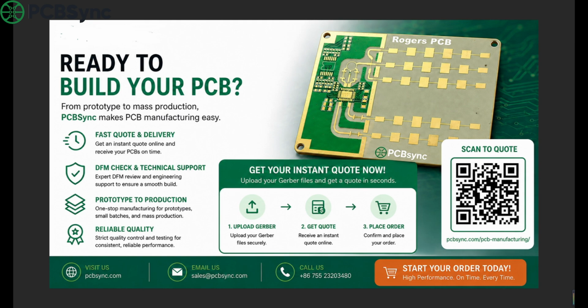In short, RO4003 is more processable than PTFE alternatives, but key challenges remain in stack-up, impedance, dimensional compensation, and supply stability. When designing, use the correct design DK, and before production confirm the actual material copper thickness, finished board thickness, and impedance compensation. Only then can you reduce the risk of frequency deviation or poor impedance in the first prototype.